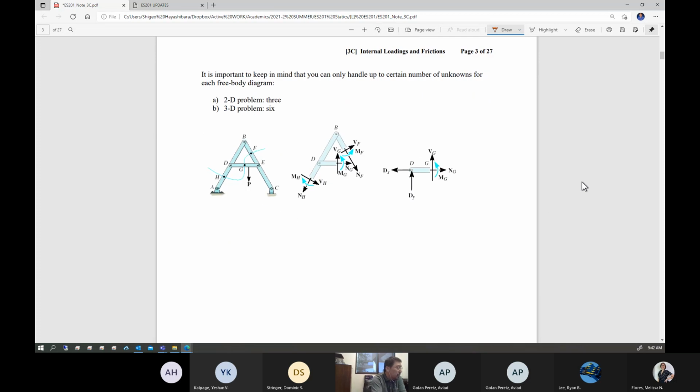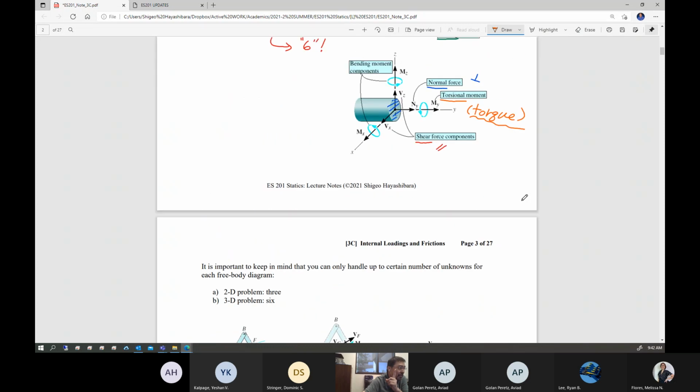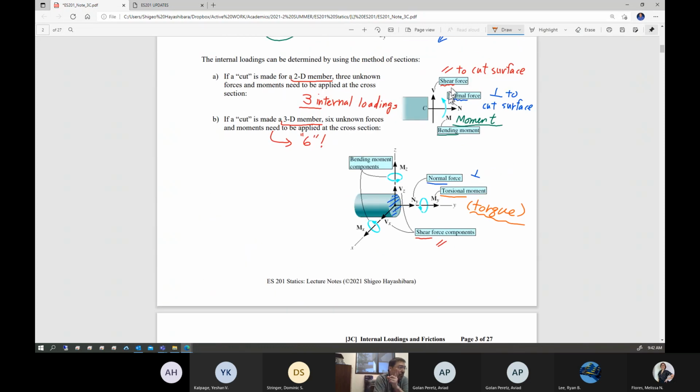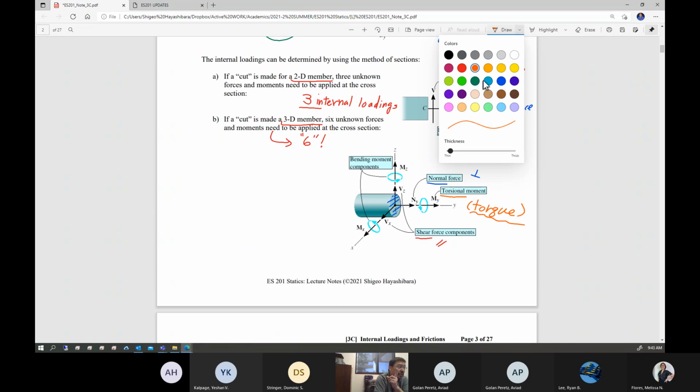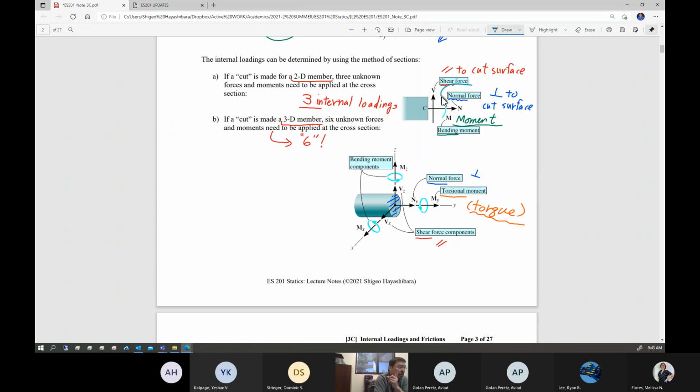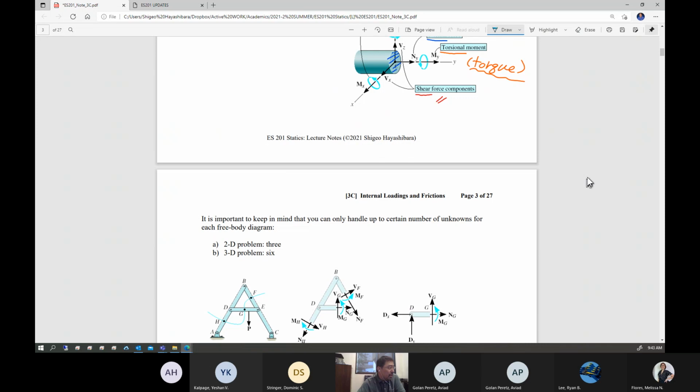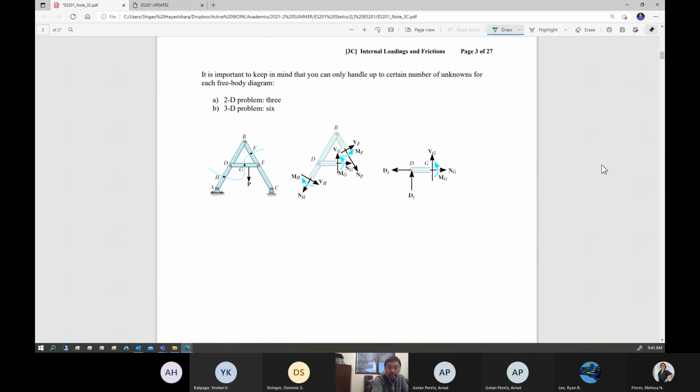So this is something we already did, to do a truss analysis. Now, this is no longer truss. Truss is a two-force member, so if you cut through each member, at each cut section you're going to introduce only one force, essentially the normal force, because it's a two-force member. Now, you're dealing with machines and frames and more general types of structures.